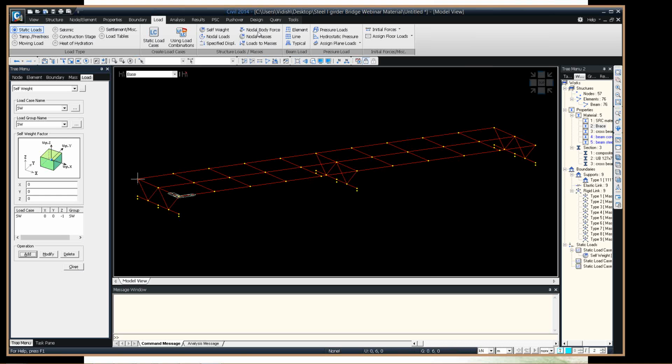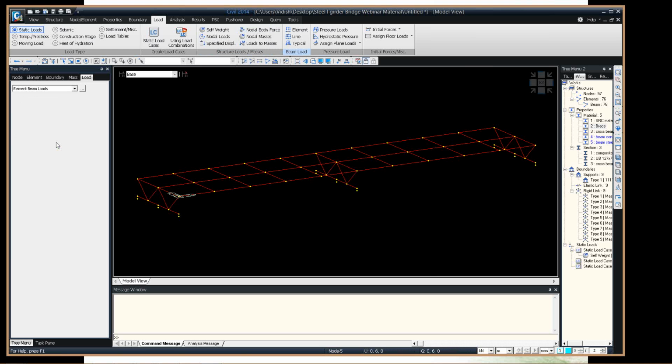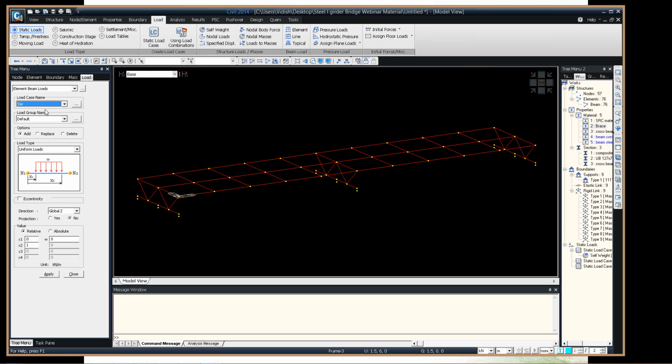So now that that's done, let's go for the element loads. Although I've named it as parapet, I'm assuming that this load will include just about the other loadings as well, so I'm going to add them under the parapet load case. So let's say -5.